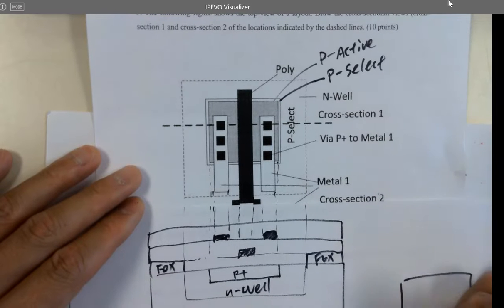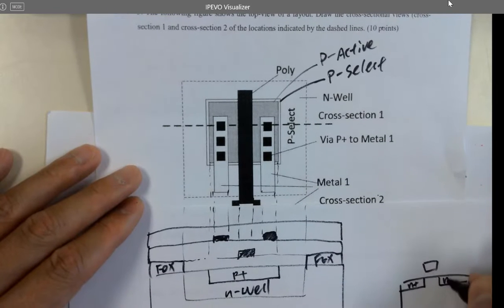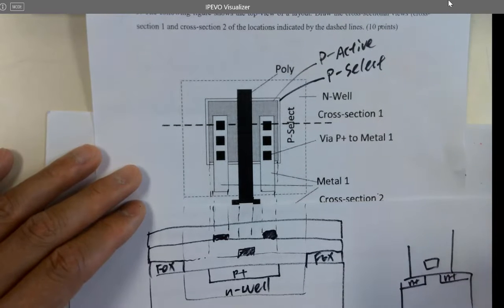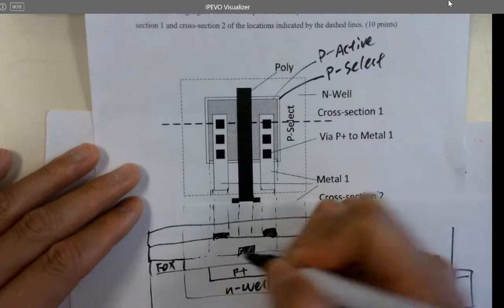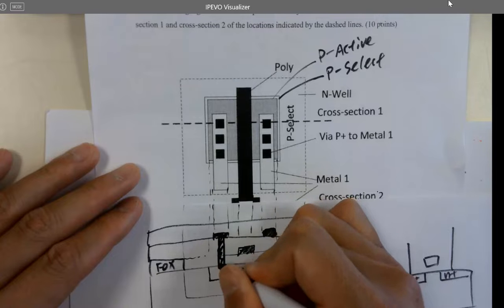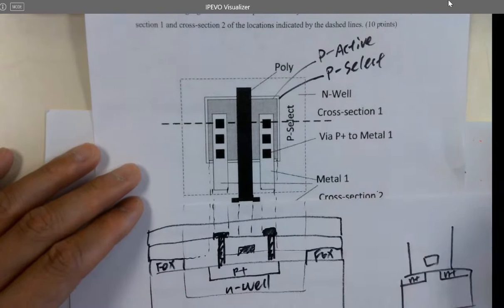Yeah, for example, the NMOS, right? Okay, you got wires connected to these terminals to form the transistors. Definitely you have metal. You have vias for that one. So the via is gonna drill a hole to here and here. Make the connection to the PMOS, the P plus.